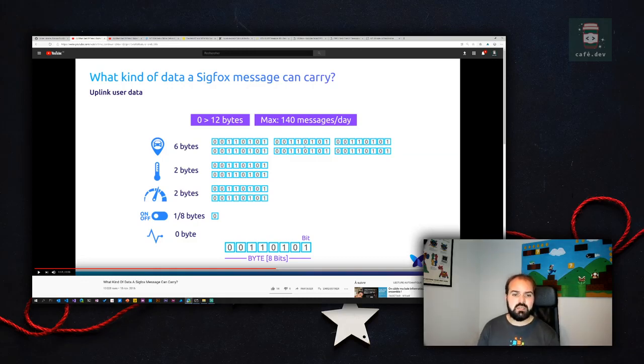As you can see, in a single message, we can pass on a lot of geo coordinates. We can pass on a lot of sensor data. So if what you're doing is simply monitoring the temperature in different parts of a building, Sigfox or LoRa can be a great fit for getting your device connected to a network. But it's not really useful to send a picture. I would definitely go beyond what this kind of network can support just by sending only one picture a day.